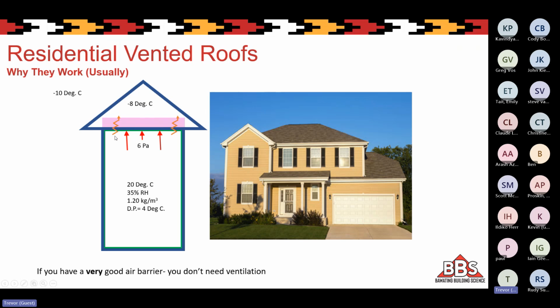So we also have just heat loss. Even though we do our best to insulate roofs, there's still going to be a certain amount of heat loss occurring through the attic insulation. And the attic space itself is always going to be a bit warmer than it is outside. And that'll come into play in the next slide. So if we have no air leakage, we have a perfect air barrier, we have no problem. We don't even need ventilation because we have no moisture in this attic to deal with.